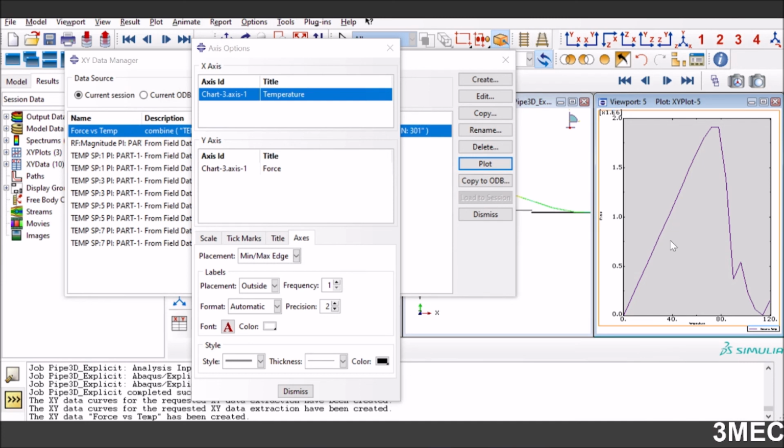Again, to validate your own model, you have to use your own boundary conditions, loadings, and the material properties, etc., friction properties as well. But also you need to do a mesh sensitivity analysis, as I haven't done that, and you might have to change and play around with different types of mesh to see which one converges or gives you the right results.